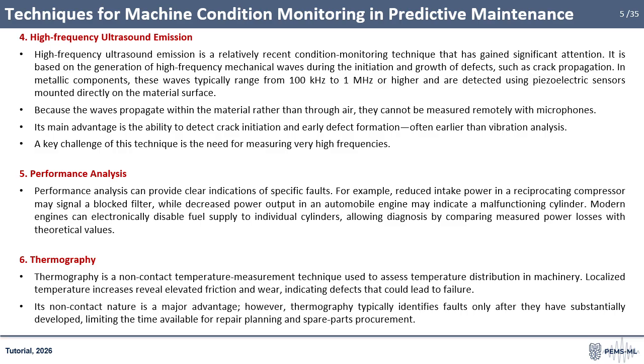High-frequency ultrasound emission is a relatively new condition monitoring technique that has gained increasing attention. It is based on the generation of high-frequency mechanical waves during the initiation and growth of defects, such as crack propagation. In metallic components, these waves typically range from 100 kHz to 1 MHz or higher and are detected using piezoelectric sensors mounted directly on the machine surface.